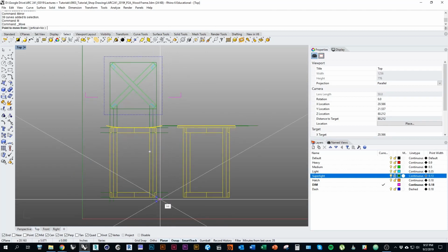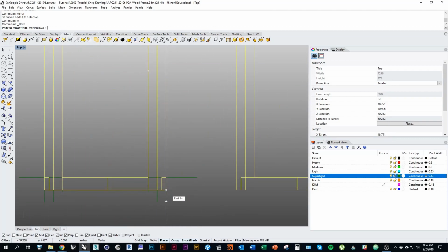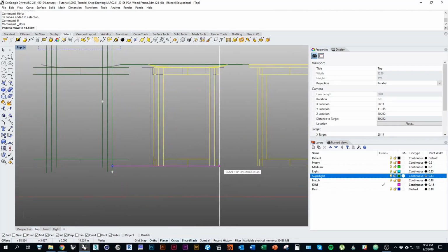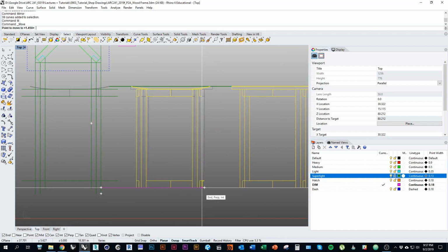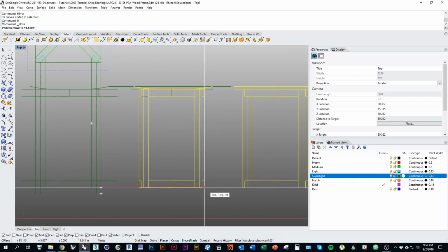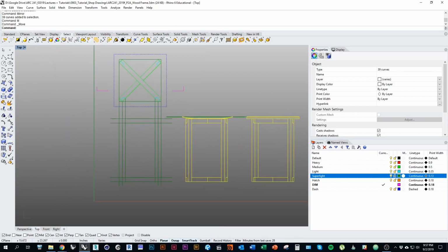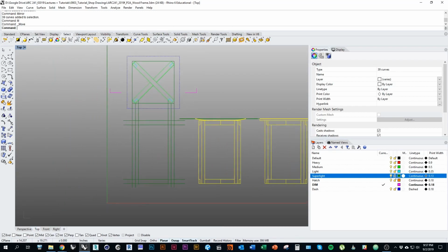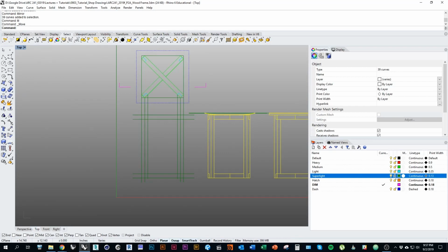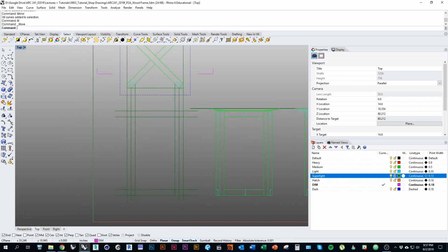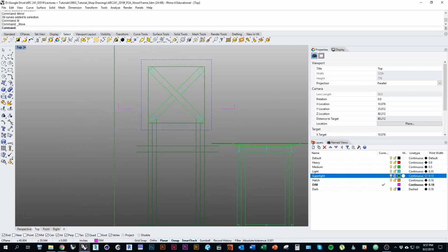So I'm going to select all these drawings, and I'll type in move, and then I'll snap to this corner, and then snap that drawing to the same corner where the other elevation used to be. That way, when we draw this section, we'll have even spacing between our three drawings, just to keep our layout cleaner. Okay. Now I'm going to go back to the layer super light.